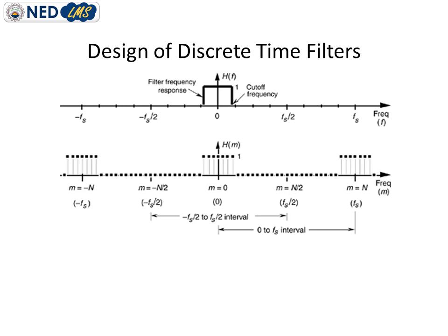You can also notice the difference between the first and second plot. The first one is the continuous frequency response and the second one is the discrete frequency response. And you can notice that in the discrete frequency response there is a periodic repetition, because discrete frequency domain representations are always periodic with the period equal to the sampling rate, which is fs.